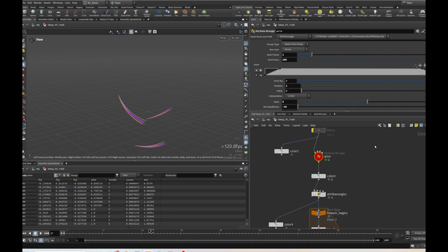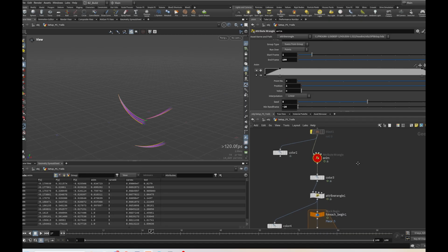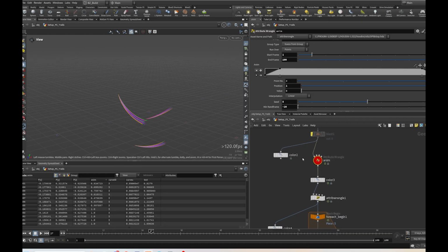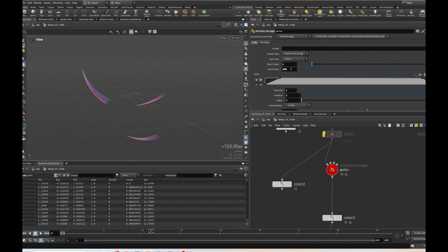So we need to create another node to be responsible for the speed, and we can use this triangle here to initialize the length. Alright, so let's set this end value to 250, and we can tackle the extension of the effect first. And one of the best solutions I can think of is using the modulo function. It's basically you can repeat this effect for every certain frame.